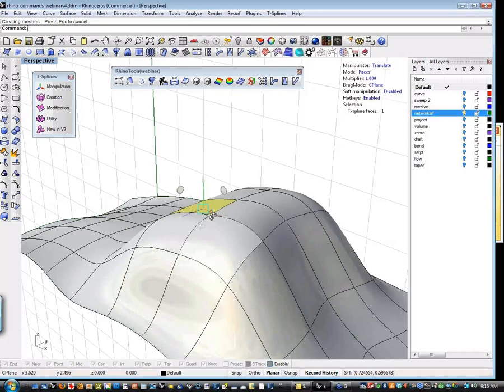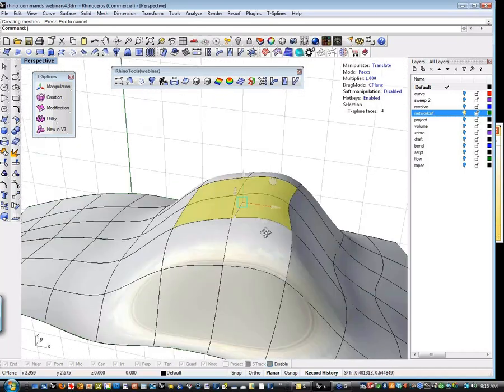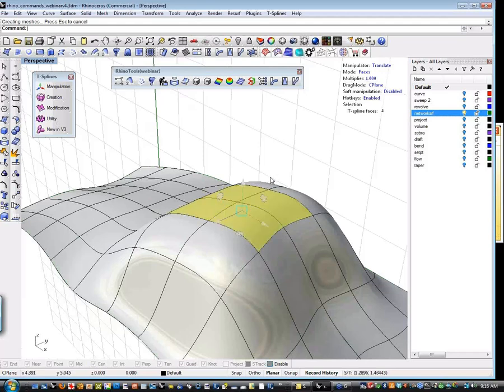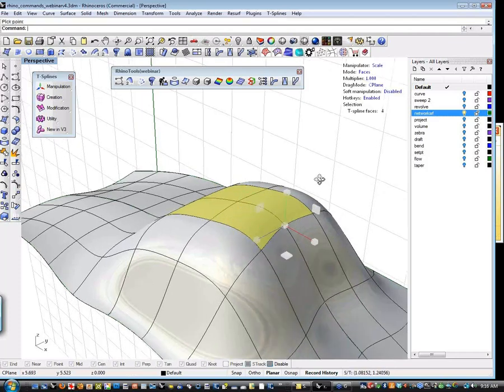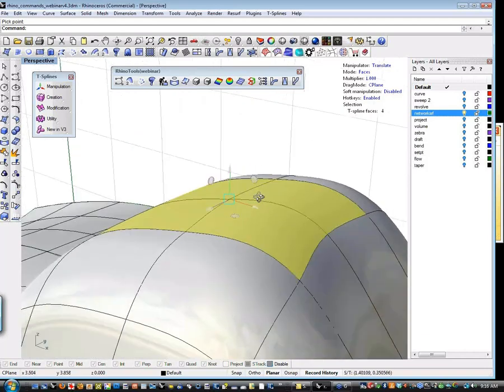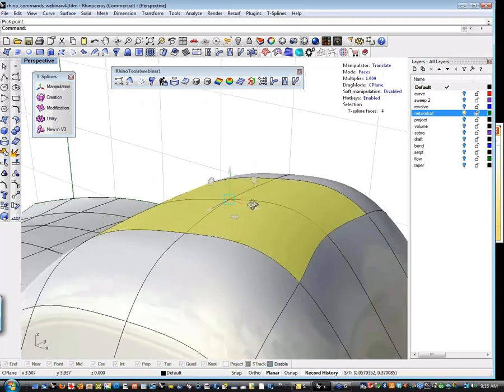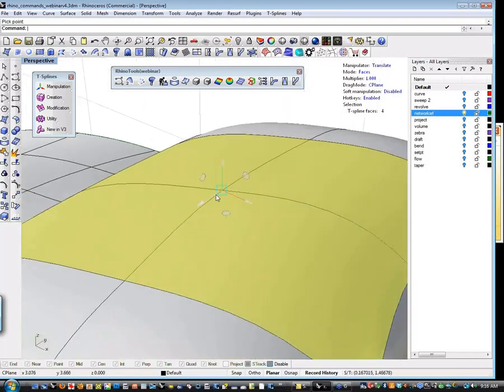Absolutely. The T-Splines manipulator is basically a simple triad, just like you've seen in a lot of other CAD programs. There's move, there's rotate, there's scale, and then the T key. If I hit the T key, I can move the manipulator, which not a lot of people know right off the bat. But the T-Splines guys have additionally added these construction plane discs, and basically each disc corresponds with a pair of manipulator handles.